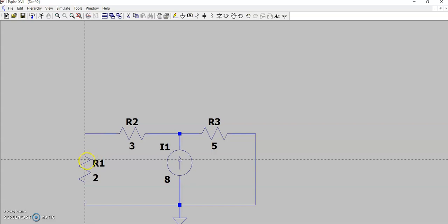That is how you simulate the circuit using LTspice. So it is very simple. You have to make the schematic first and simulate it. Then you obtain the voltage as well as the current. So what you have done in network theory, all the calculations, all the mesh analysis, loop analysis, everything you have done using a large set of equations, can easily be found out using this LTspice. So hope this one is clear to you.